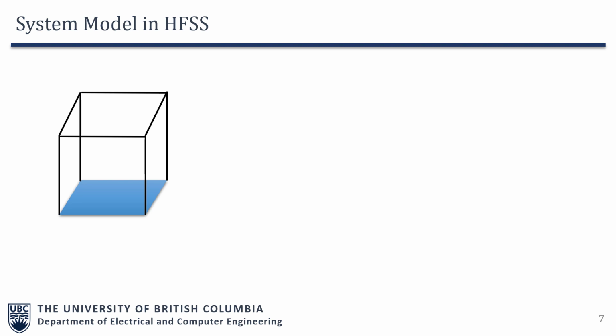And by the definition of the waveguide, the electric and magnetic field distributions would be confined by the walls of the waveguide as PMC and PEC on these two ends. On the other side of this waveguide, we would be launching the wave. That means we would define a wave port. That's the point of excitation, right? The height of this waveguide, or the height of this box, should be at least a quarter wavelength at the operating frequency.